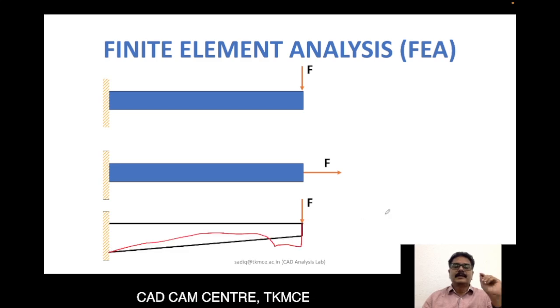Then can you go for that equation? No. There we apply the same finite element method. What will we do? We will discretize the whole domain into equal spaces having similar properties, and then we will identify the total property of the object by computing that property of each element. So in the previous case of computing area, we took one element as the area square, 1 square centimeter, and the property was area. Finally, we added all the small areas, and then we identified the area of the object.